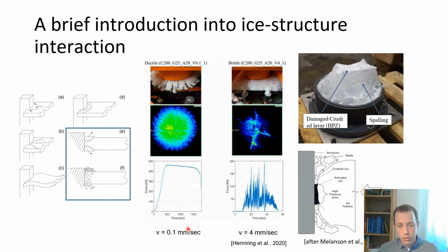Basically, you have to subdivide the ice loads into ductile loads and brittle loads. At small velocities, here as shown at 0.1 millimeters per second, ice behaves ductile. You see no force oscillations, and the process is mainly limited by continuum mechanics and continuous disintegration.